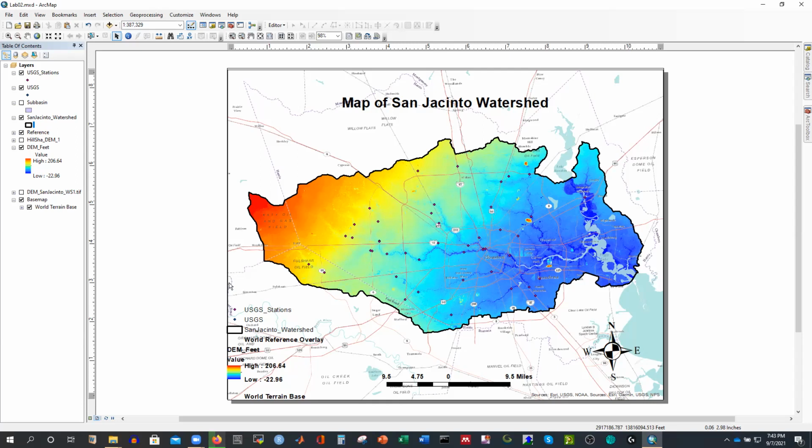Today I'll also show you a very basic trick. Previously, we specified the basin parameters, the reach parameters, and everything individually. But today I'll show you how to do everything at once. If you want to select a method, I don't need to click basin by basin. I'll select the method for all, like selecting the loss method for every sub watershed. That's the reality, right? We select the same loss method for every sub watershed, and the same routing method for every stream.